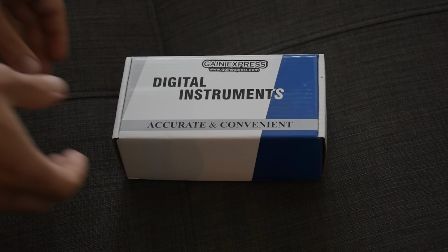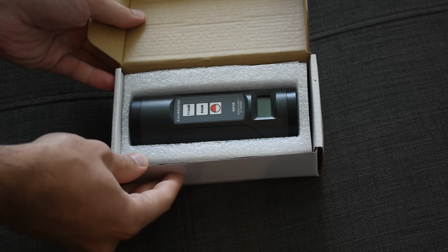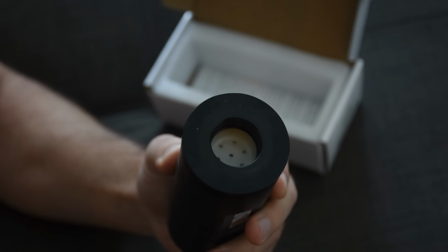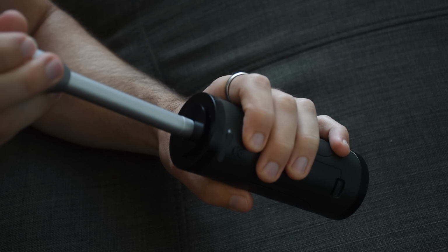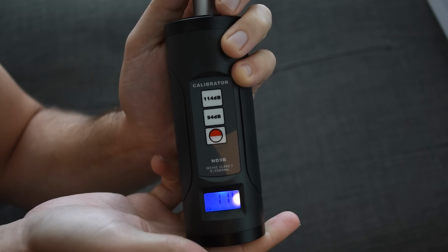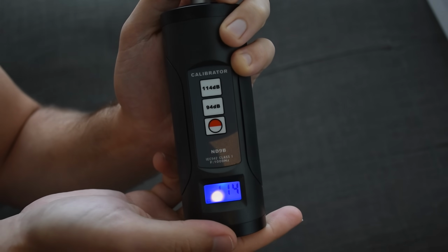The only thing left to do is calibrate the setup, which is what this sound level calibrator is for. It outputs a 1 kHz sine wave and generates a known sound pressure within this cavity. All we need to do is insert the microphone, turn on the calibrator, record a few seconds of audio, and now we have a reference waveform that we can use to calculate the microphone's pressure sensitivity and calibrate our readings.